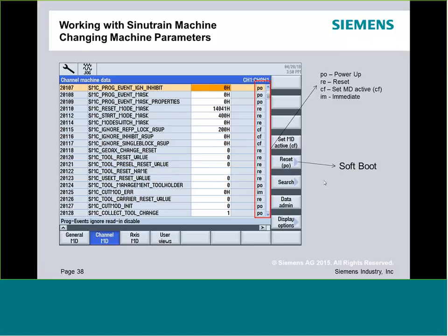If you don't want to use this, you can do a machine shutdown and just jump right out to the previous screen within Sinutrain and relaunch the machine. That does the same thing. A lot of guys think you've got to completely shut down all of Sinutrain. You don't. It just has to reboot the physical machine. But this is a good indication.